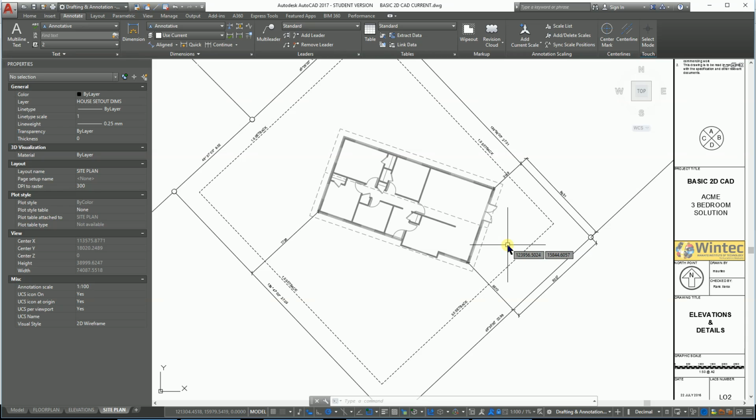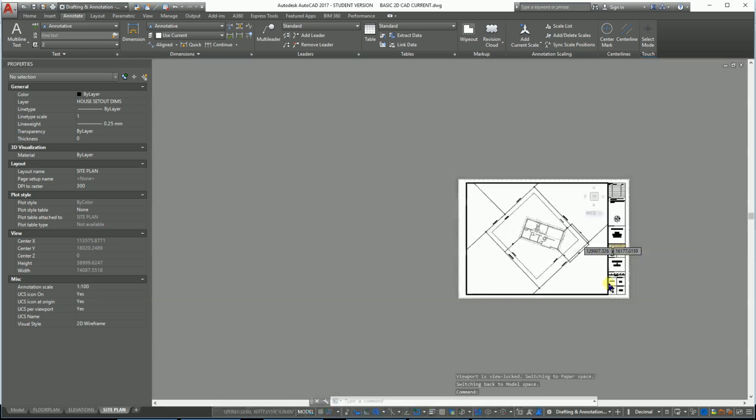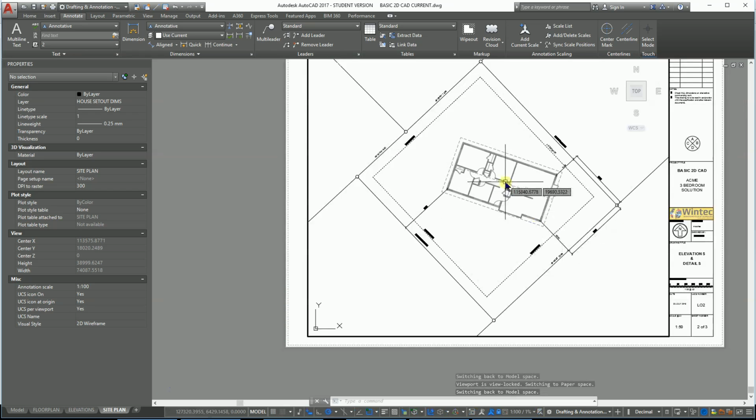The next thing to look at would be, we would be starting to look at the garage and getting the garage there. So the garage is going to be drawn in another separate plan and then XREF'd in. So that's what's going to happen next, and we'll see where things go from there. We may do a little bit of, try and get a little bit of text into that house. Just might make things look a little bit more civilized, so that we can work out which rooms are where. But that's something for the future.